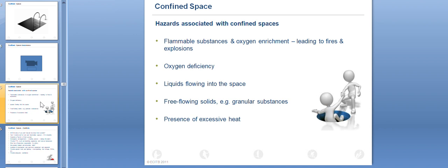That is the safe zone of oxygen for humans. The minimum we can go is 16; below 16 there is shortness of breath, unconsciousness and many other health effects. Above 22.9, like 23 and more, is also enrichment, which can adversely affect our health. So we have to do the work between 19.5 and 22.9.